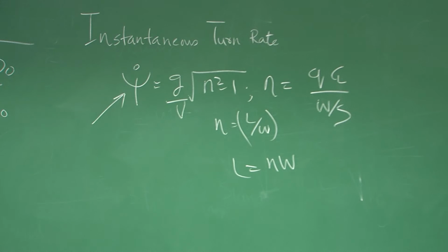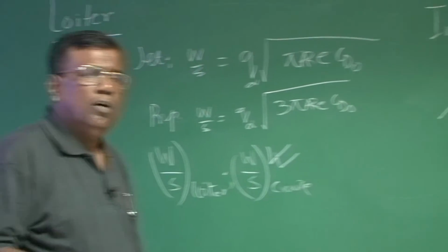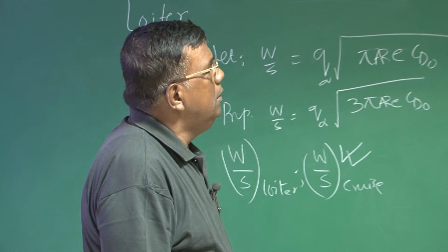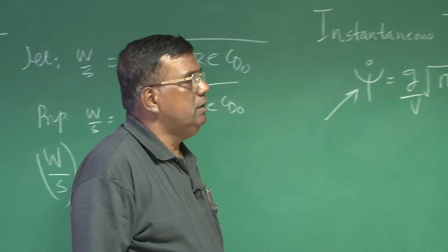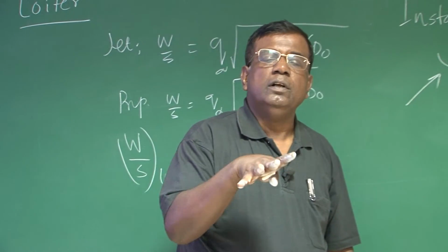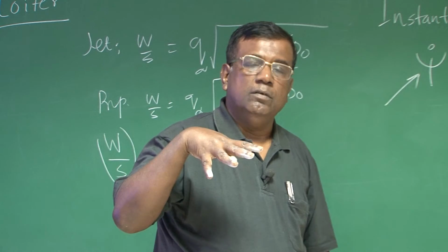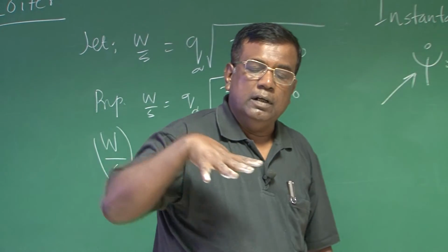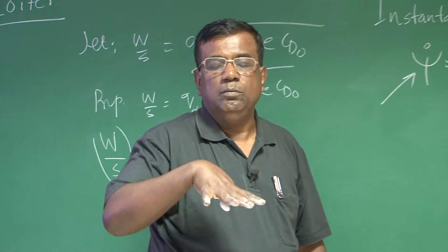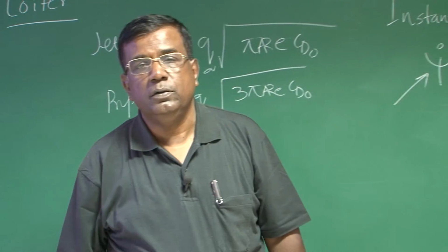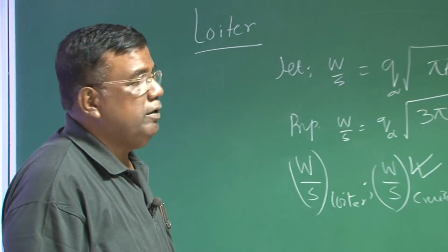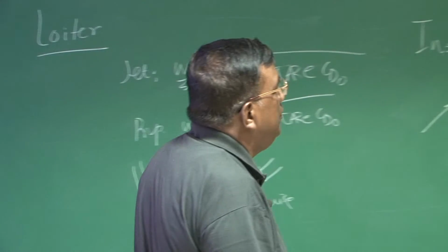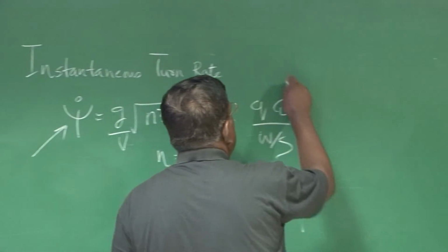This is more important for fighter airplanes, mostly in a dogfight mode, fighter mode. And we have realized that during instantaneous turn rate, the drag will increase, so there is a possibility, instantaneous turn rate when you go to maximum turn rate, but you lose the altitude, right? That may not be advantageous for your dogfight mode. So we talked about sustained turn rate.